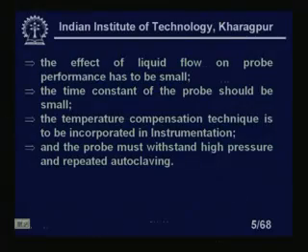Then the probe must withstand high pressure and repeated autoclaving. This is also a problem, because in bioreactors, whenever we use sensors, one important thing is that we have to autoclave, that is, sterilize. Autoclaving is like a household pressure cooker.